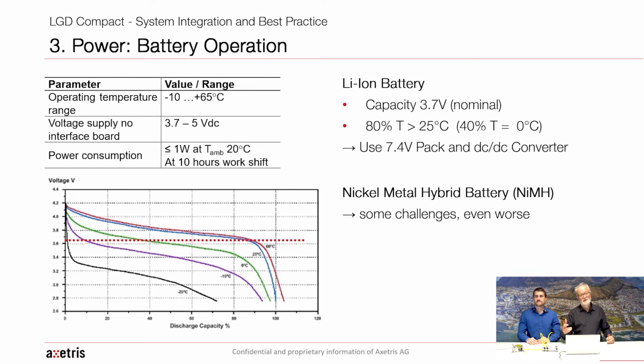And then you have to think about the power consumption. That might be 1 watt for our unit and something for the little computer and something for the pump. And maybe you want to work a 10 hour work shift, so you have a full battery, and when you go home in the evening, it's empty, you reload it during the night. This would define your capacity.